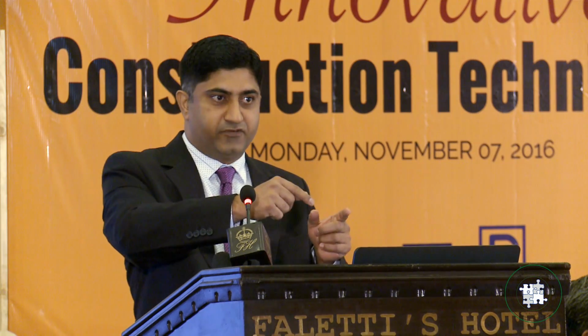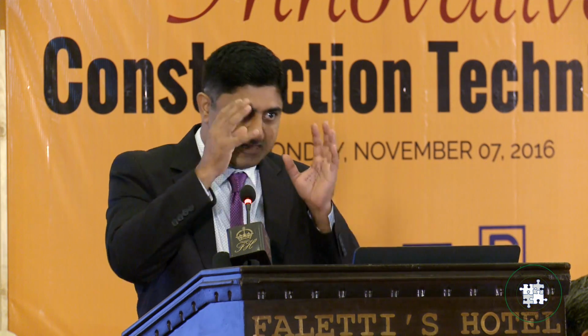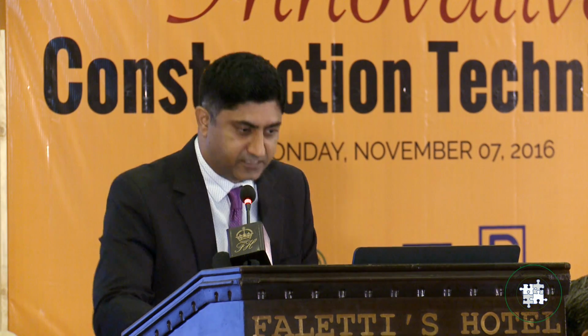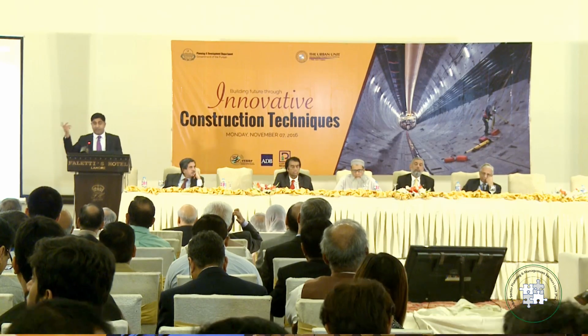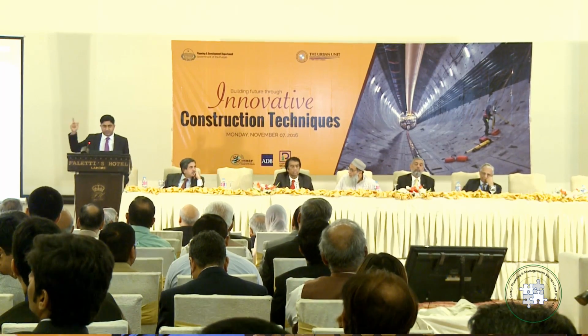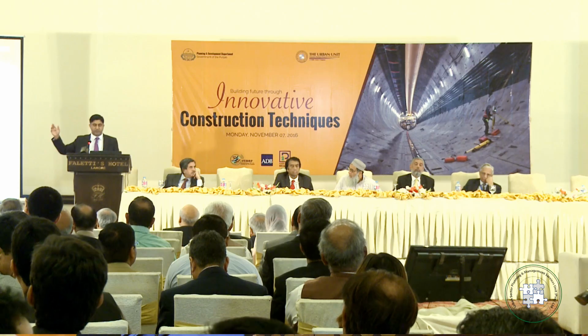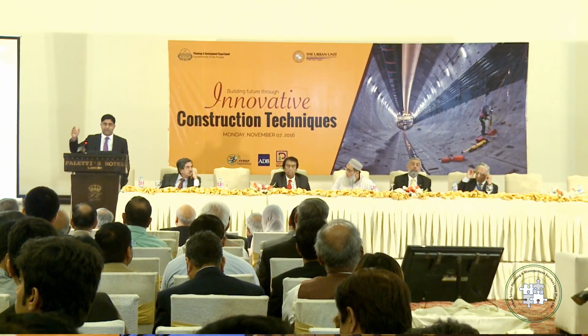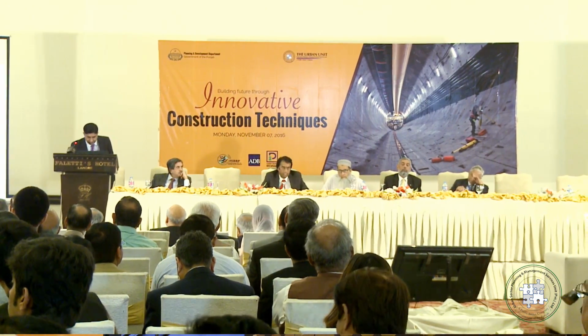We will see in real time whether this is true and how it actually acts. So as a result, the deformation still happens because, like I said, pavements are designed to fail at the end of the day. The level of deformation is very small as compared to the unstabilized section. So let us see quickly.